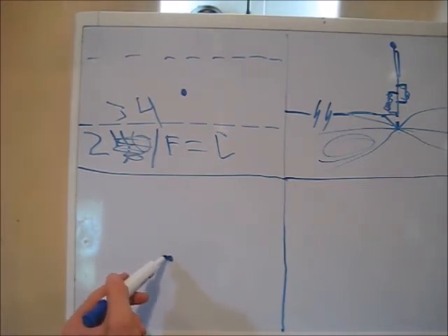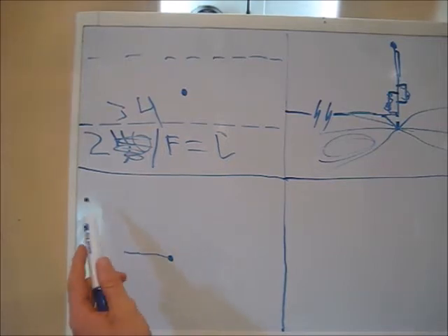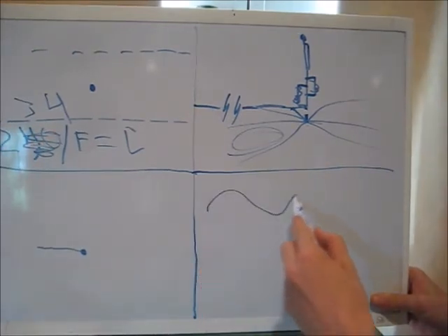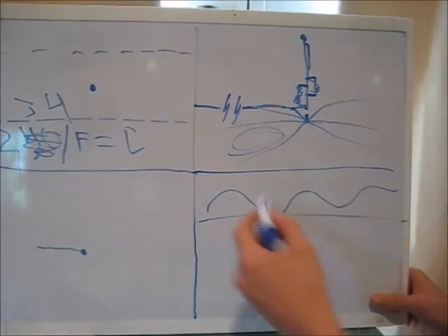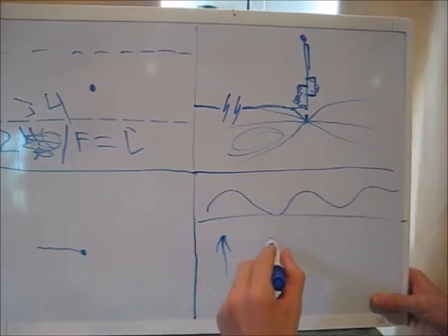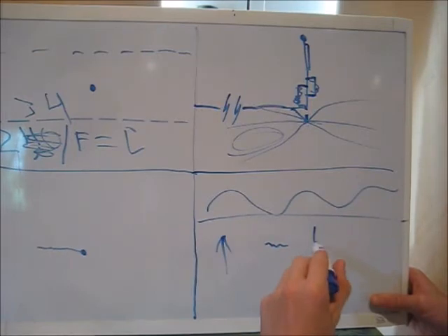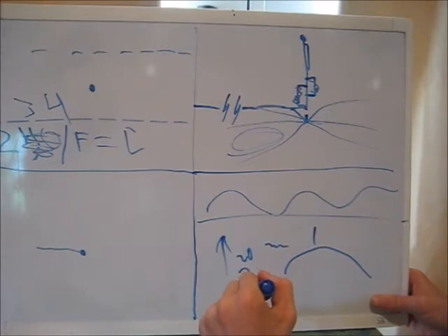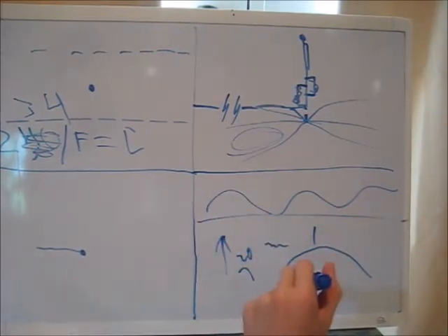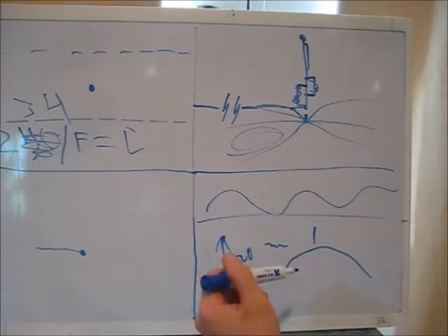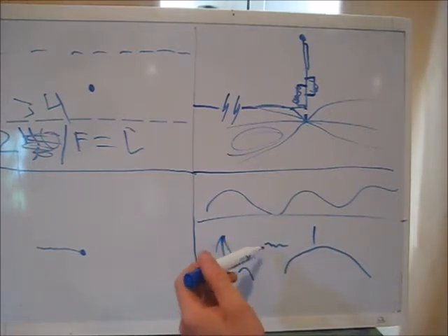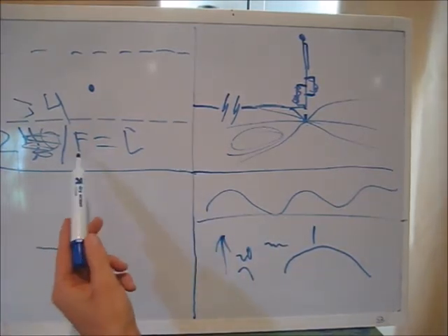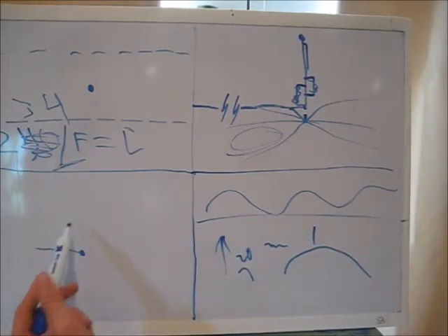So different radials are different lengths, and the standard is, this is just a rule of thumb, I'm going to use this box over here for a second. Wavelength: the higher up in frequency, the shorter the wavelength is. So at 1 megahertz, my wavelength might look like this, compared to at 20, my wave might look like that. It gets smaller and smaller. This is not to scale, trust me. At 1 megahertz, you have about a 200 meter wavelength. But that's the concept there. So as you increase frequency, as seen by this mathematical equation, your radials are going to get shorter.